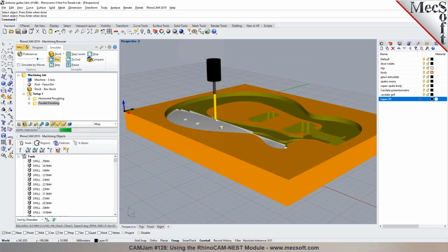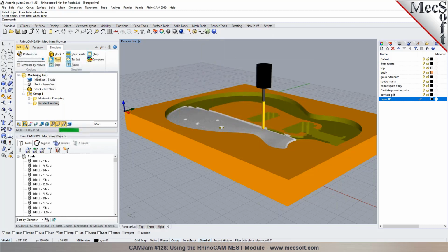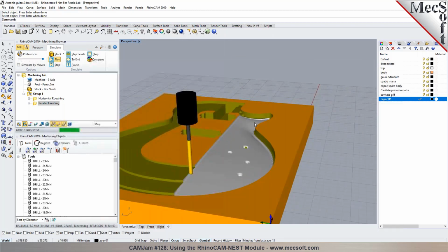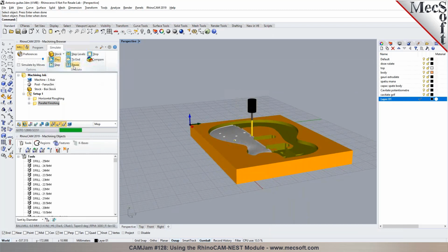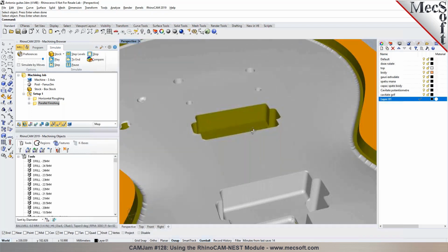So once you have programmed the finishing operation, you could go back and program those pockets, finish those pockets, open pockets, and then you flip it over. You cut the features on the back of the part, and then post-process the code out to your machine. So with the Pro, we can program multiple sides. You can do a pause, then pick simulate to end. I'm selecting simulate to end, so it basically runs the simulation all the way through to the end, so you don't have to watch the simulation in every step. So there's the finishing operation.